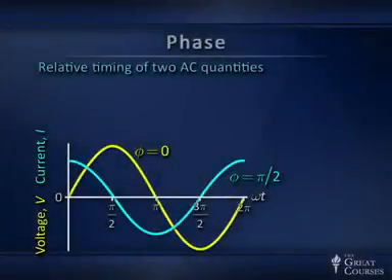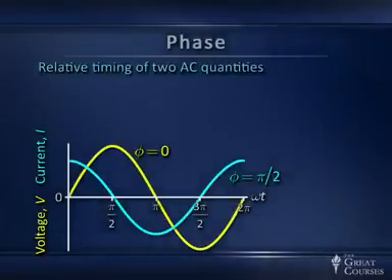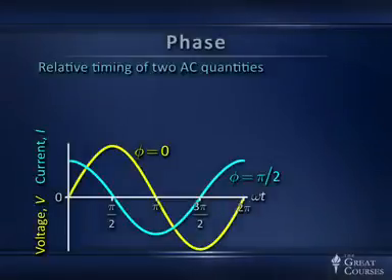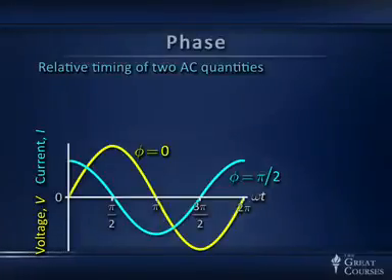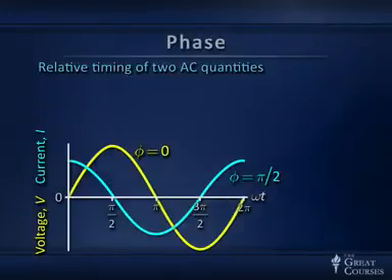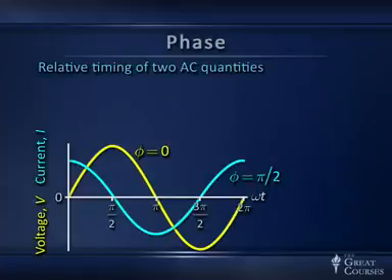So here I'm showing two complete cycles. For example, a voltage in the brighter color and a current in the darker color, and those two are both peaking and having troughs, but they're having them at different points. And in this case, you'll notice that the current, the darker curve, has peaked before the voltage. In fact, it's peaked 90 degrees, a quarter of a cycle, pi over 2 radians. Those are all ways of saying the same thing, before the voltage.